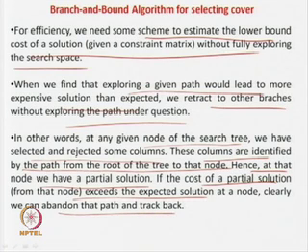So, what is it saying? At a root node, you take a left path or a right path. Left path means you do not take it, right path means you take it. The next node means you take this node, which implies that you have taken the column corresponding to the root node. That means at each intermediate node you actually have a sub-solution, that is, you have taken prime implicants A, B, C, D and so forth, or you have taken prime implicant A, not taken prime implicant B and taken prime implicant C.